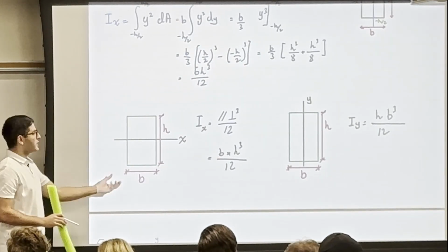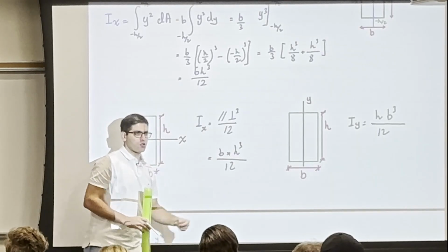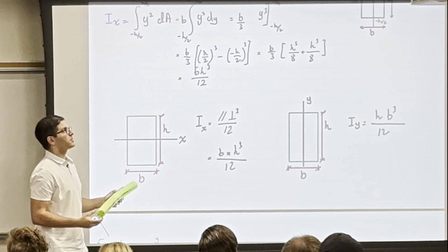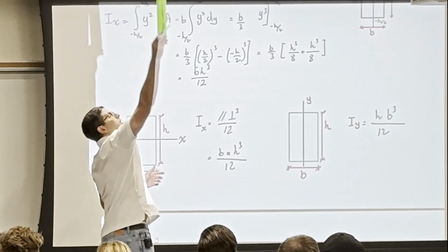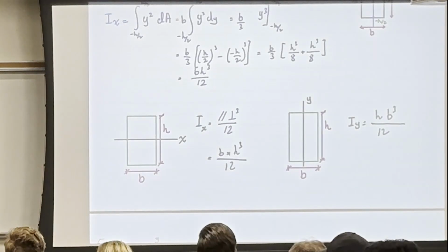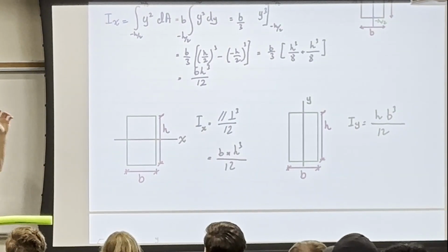And you're going to see in this equation, what is dominating here is h. Which tells you also, if this is a beam and I want to have this beam very strong in resisting the bending from the people who are above us, we need to increase its thickness.